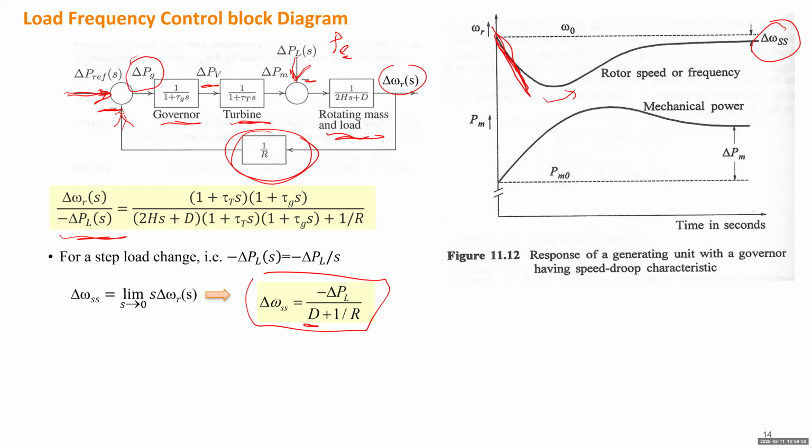The reason is the load frequency control by the governor is basically just a proportional controller. A proportional controller cannot eliminate the error of the control variable. You have to introduce some control which is similar to an integral controller. So does everybody know integral controller, proportional controller, and differential controller? Yeah. So basically, proportional controller is you measure whatever deviation you want to reduce or eliminate, and multiply that deviation by some number. Usually that number is supposed to be large enough, then compare it to the setting value. So that can help to mitigate the error.